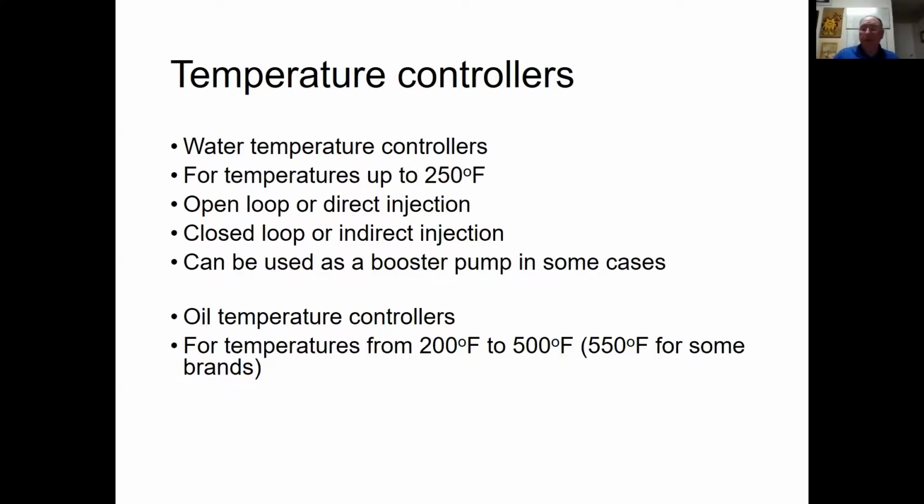They're designed for temperatures anywhere from 200 to 500 degrees, 550 on some brands. They're available in what we call heat only. There's no heat exchanger. So the application is a heat only or continuous heating application where no cooling is required. The application has to have heat in order for the product to cure or solidify, however you want to say it. Therefore, we don't have a heat exchanger in there because there's no cooling.